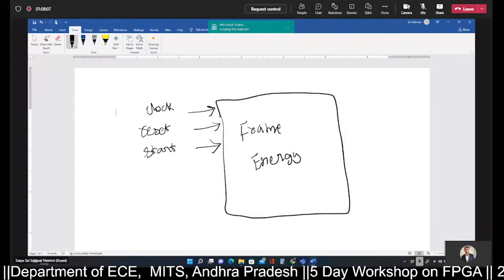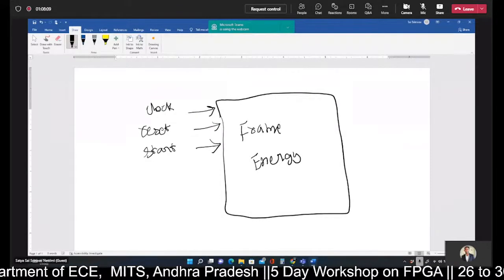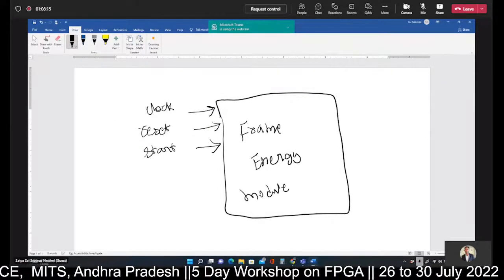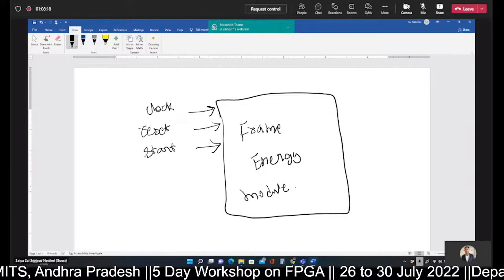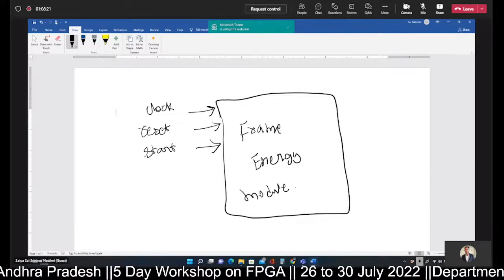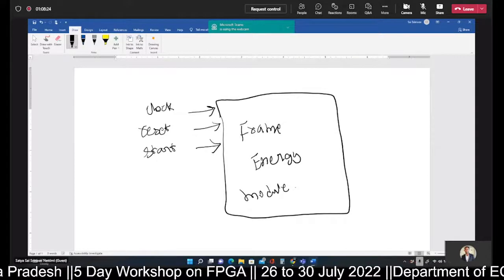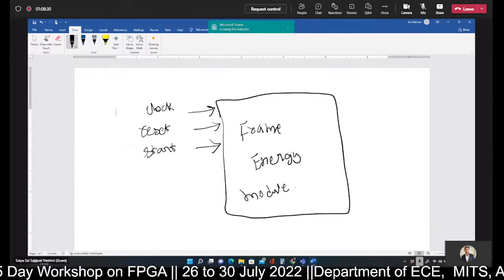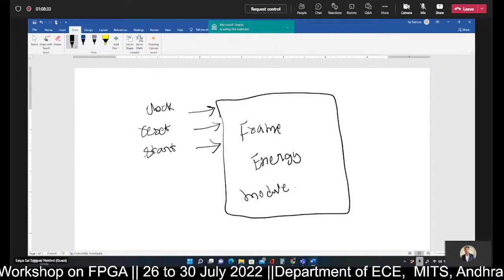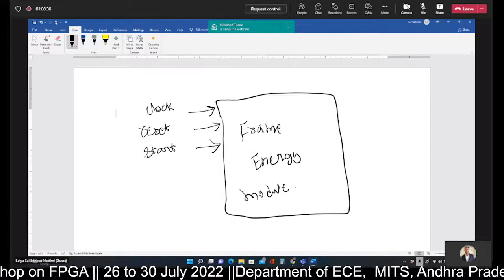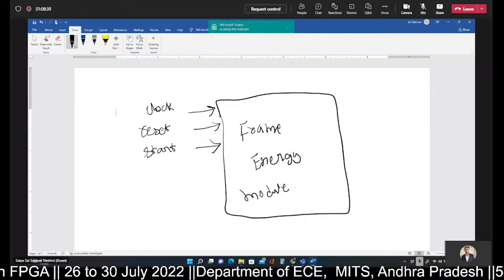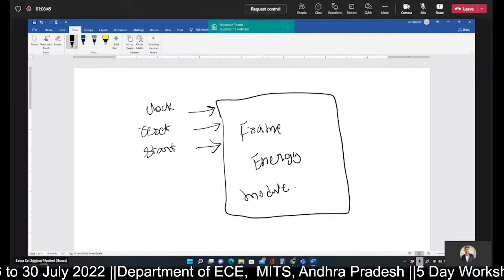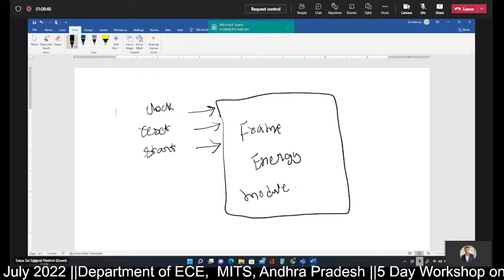When we give this start signal to the frame energy module, which is a hardware module, the module will understand that a signal is coming and it needs to calculate the energy. That is indicated by the start signal. If start is 0, then no signal is coming, and the module will be in the idle state. It will wait for the speech signal samples to arrive in order to calculate the energy. Once we give a start, the frame energy module will go into the computation phase.